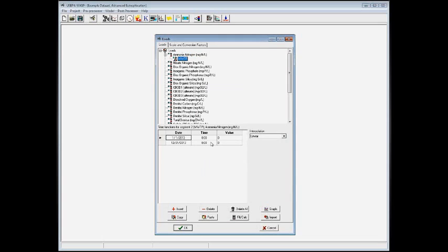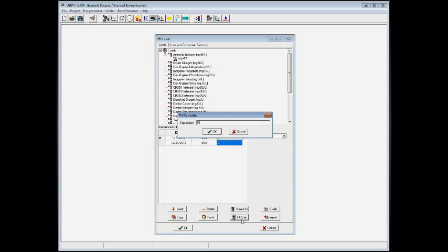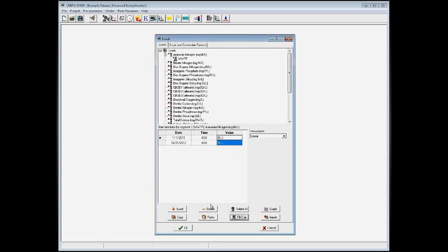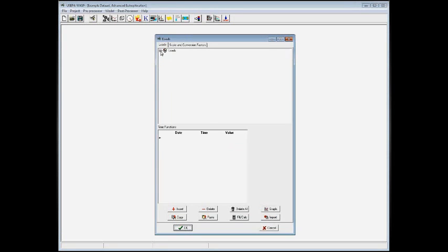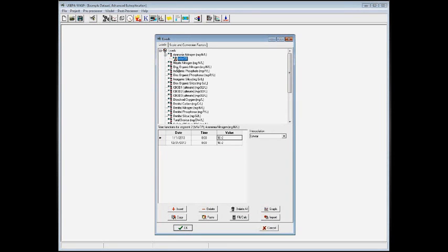Now, one of the things that needs to be corrected in the interface is under loads, under the state variable, it says ammonia nitrogen, milligrams nitrogen per liter. Well, loads are not in concentration, they are in mass, and they are in kilograms per day. So over here we're going to enter a kilogram per day of ammonia, and I'm just going to put in a relatively small number here, 0.01 kilograms per day of ammonia. And then I'm going to say OK. So that's how the loading screen works. And coming back in here, you can always go and add other loads in other places.